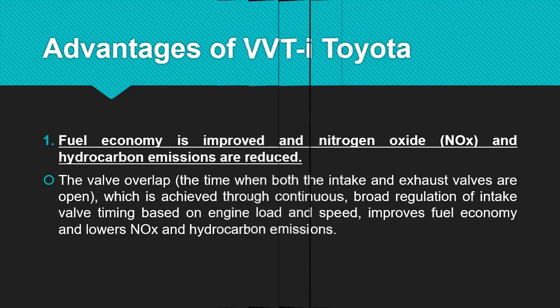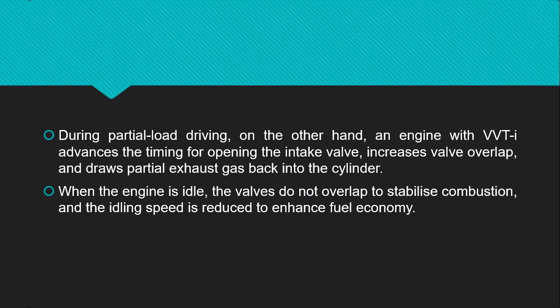During partial load, on the other hand, an engine with VVTi advances the timing for opening the intake valve, increases valve overlap, and draws partial exhaust gas back into the cylinder. When the engine is idle, the valves do not overlap, to stabilize combustion, and the idling speed is reduced to enhance fuel economy.